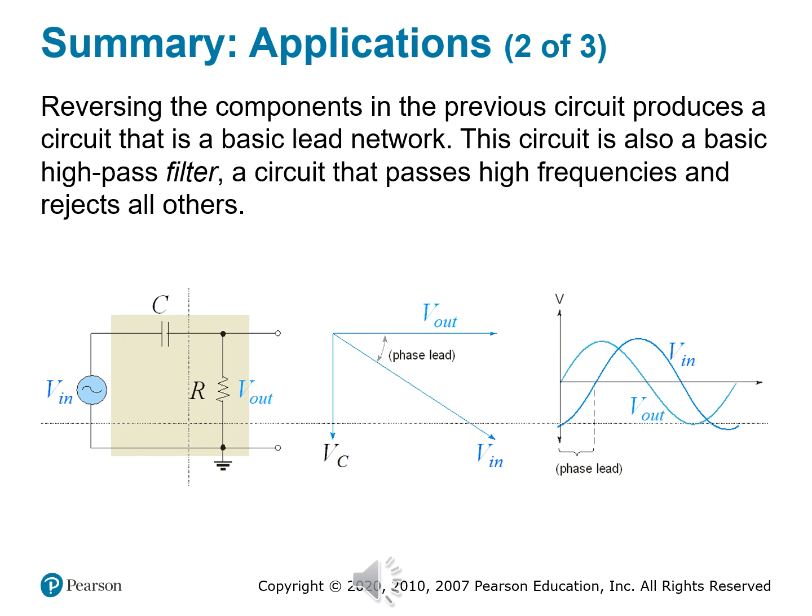For inductors, reactance increases with frequency. For capacitors, reactance decreases with frequency. So depending on which type of filter you want, lag or lead, low pass or high pass, you just got to choose the component and choose your position. Just like that, by reversing those two simple components, you flip the script. That's power. That's the elegance of analog design. So stay tuned. We've got one more application coming that connects all the dots.